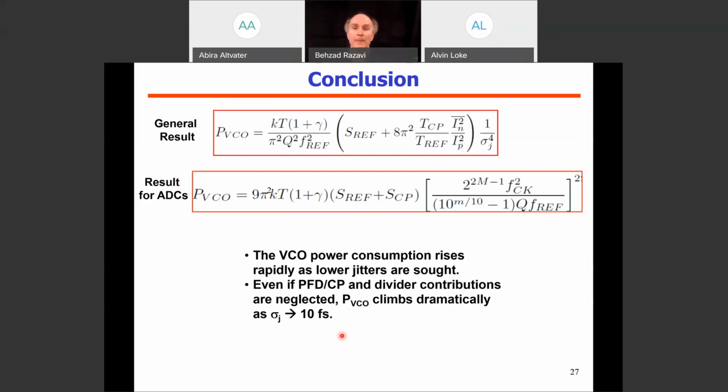Okay, and so to a related question, in these PAM4 high data rate SerDes, obviously interleaving. So really, from your perspective, you don't see the PLL power necessarily going down because essentially you still need accurate phases, right? That is true. If you are looking at the jitter contributed by the VCO, if you remember, it was not even much dependent on the output frequency anyway. So whether we have a low frequency VCO with multiple phases driving an interleaved A2D, or just a single high rate VCO driving a single channel, there's not much difference in the trade-offs that we face here. Got it.